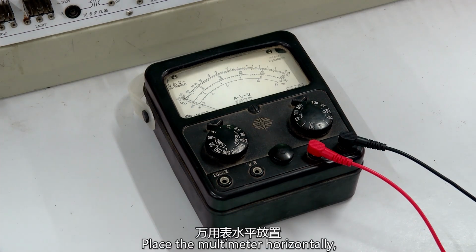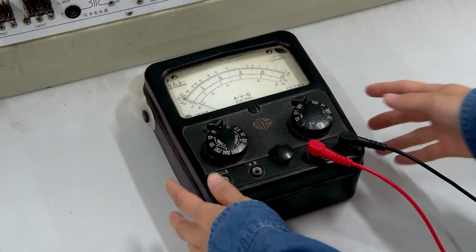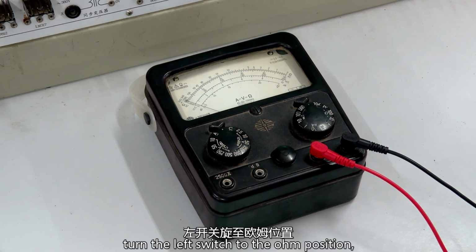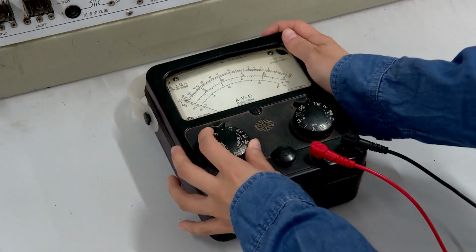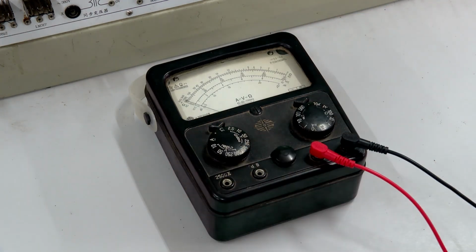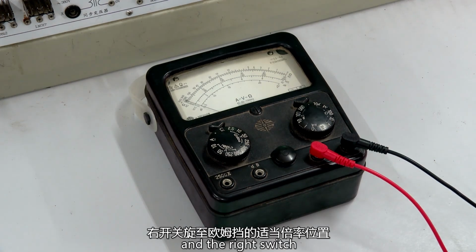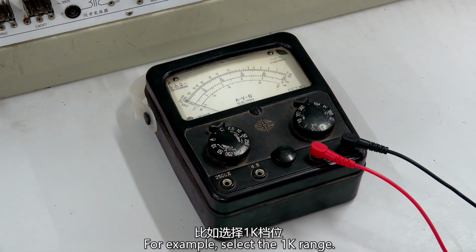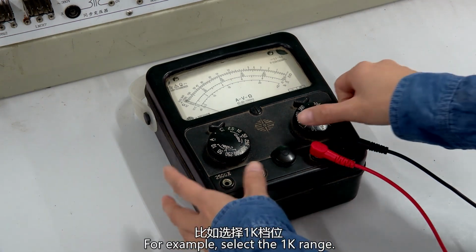Place the multimeter horizontally. Turn the left switch to the ohm position and the right switch to the appropriate range on the ohm meter. For example, select the 1K range.